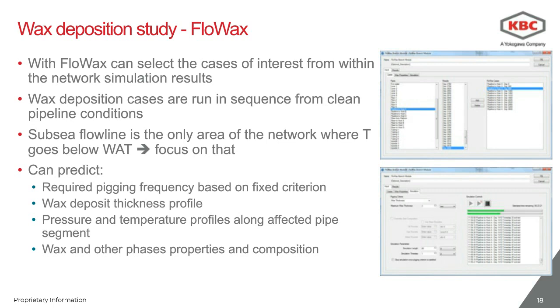From the wax deposition simulation, I will obtain information about the required pigging frequency, having set a fixed criterion for it. I will gather information on the wax deposit thickness and its profile. I'm going to have information on the effect of the deposit on the hydraulics, on the pressure and temperature profile. And because the simulation is fully compositional, I will also have all the information about physical properties and composition of the phases and composition at the inlet and outlet of the flow line.